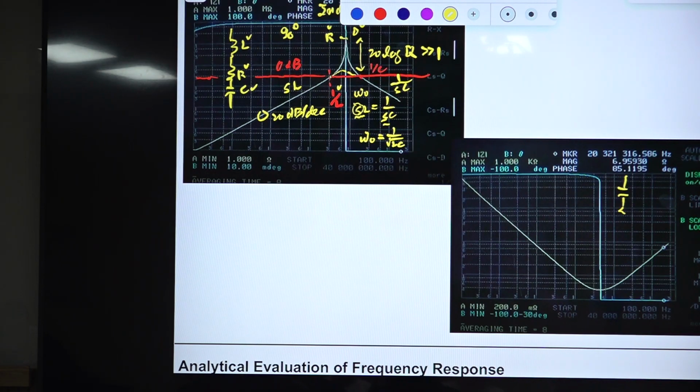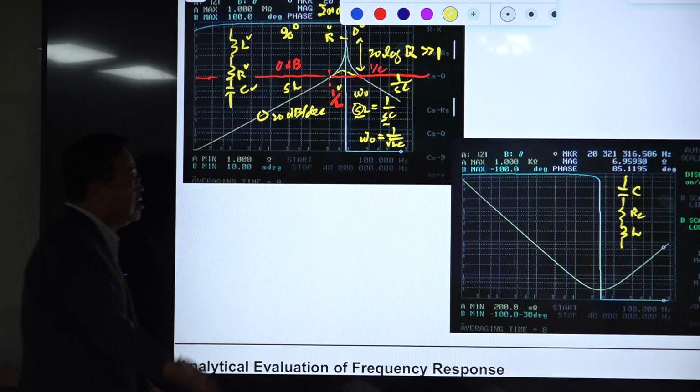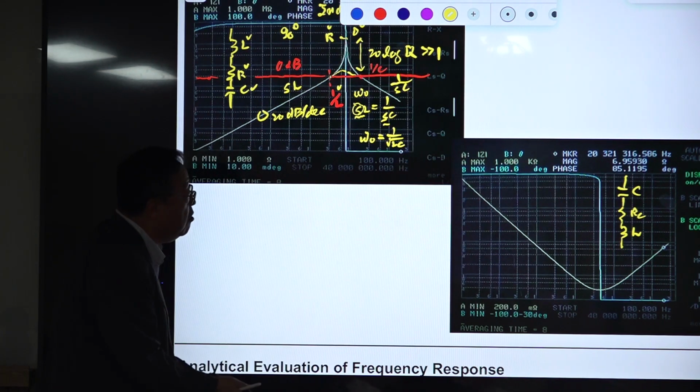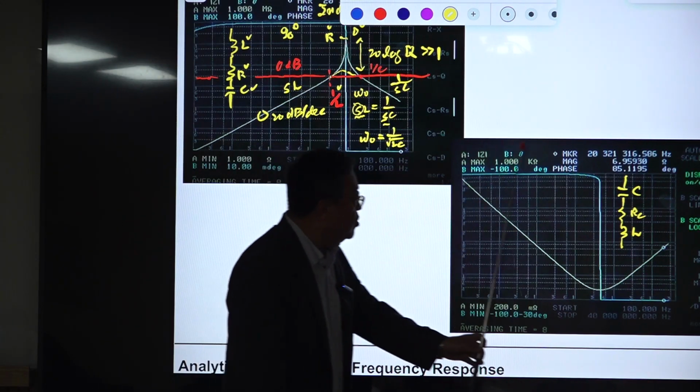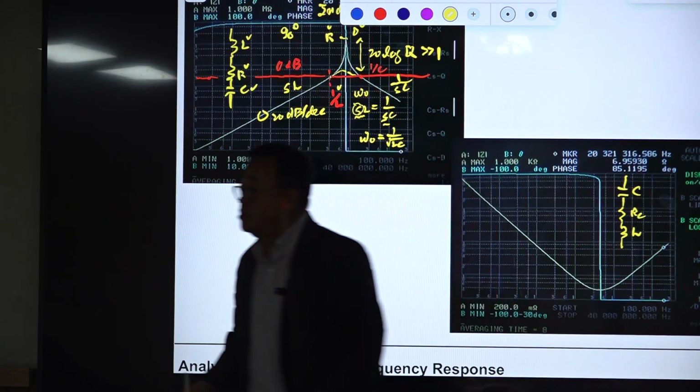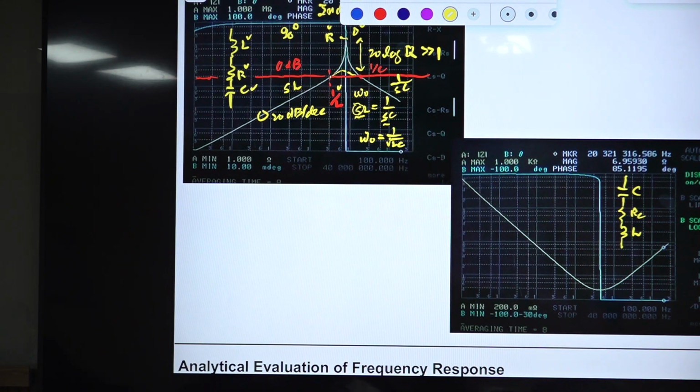Of course, you have a capacitor, so the capacitance is large, and this is the ESR of the capacitor. It has some resistance and inductance here. So this same LCR circuit represents the practical circuit model of a capacitor, and this part over here is dominant at low frequency. Okay, so this is again the 1 over SC curve.